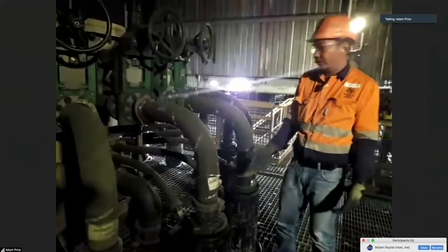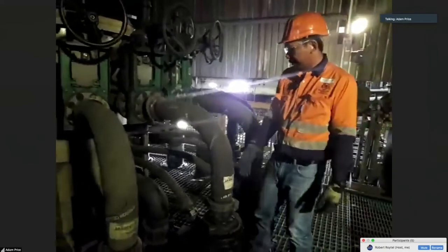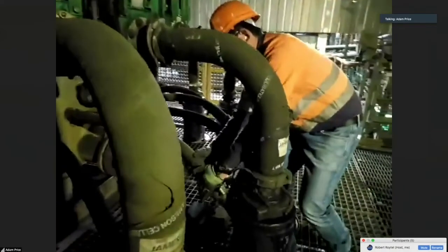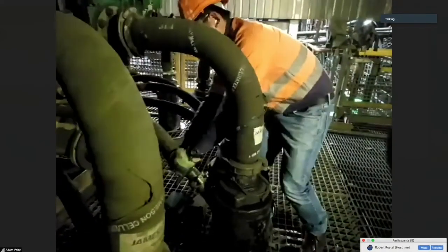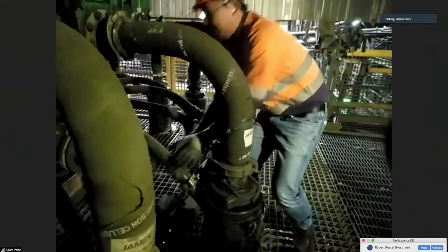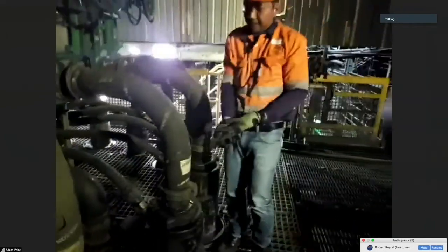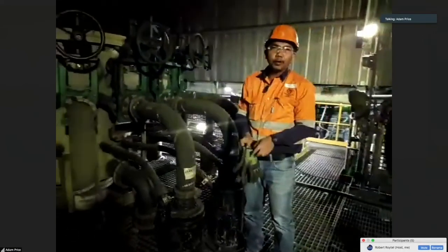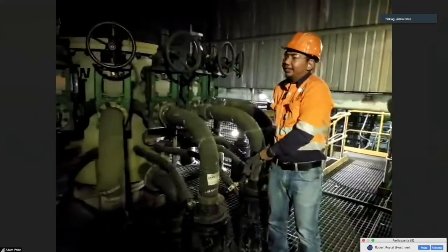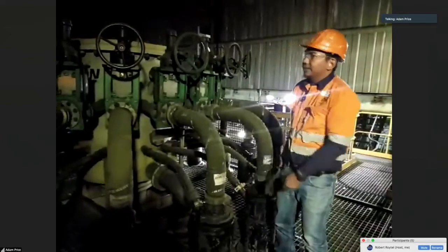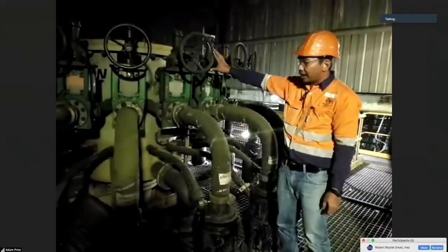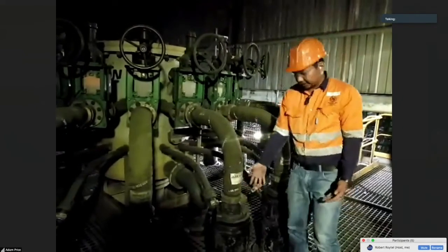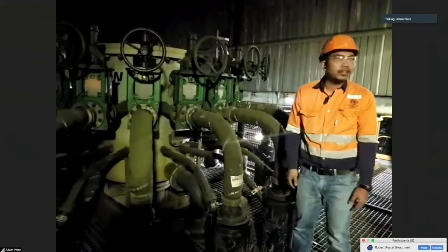Basically, what it would take is just removing the air intake hose and having a feel to see if they have a vacuum in them. So in case there's no vacuum, that means the downcomer is blocked. And what it entails to unblock the downcomers is very easy. We just have to close this valve, and then once it's isolated, we just have to undo these 2 flanges, which takes about 5 minutes, so it's very easy.